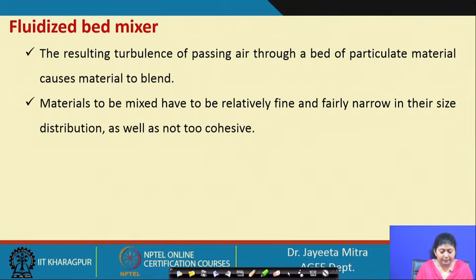So, materials to be mixed have to be relatively fine and fairly narrow in their size distribution, as well as not too cohesive. If they are fine particles, then proper fluidization will be easier, and if they are cohesive, then they will not be exposed properly to the fluid stream, and proper mixing will not be done.